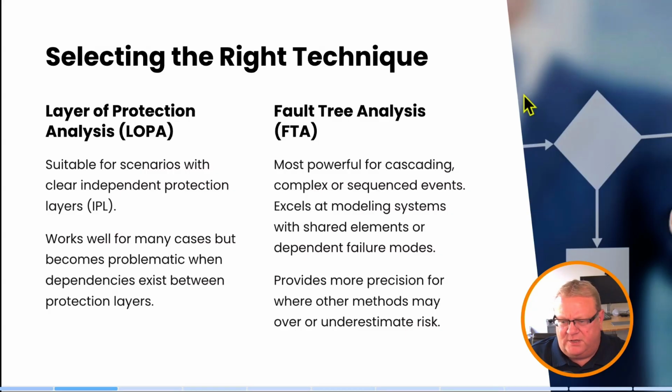It's a commonplace thing, clearly in the process sector, to separate out the protection layers such that they don't have dependencies. But oftentimes there's cases where there's a mixture of a process control layer and a safety instrumented system layer having some common equipment. Now, of course, if you're still at the design stage, you can choose to redesign so that they don't have common equipment. But that's not always an option, especially if you're in a plant that's already running without doing any modifications.